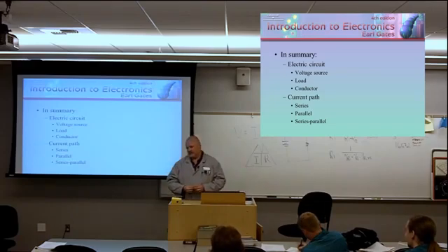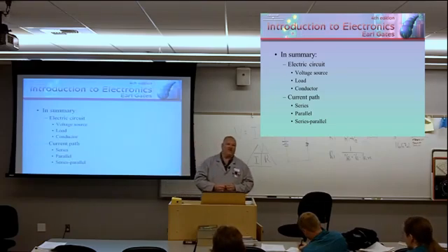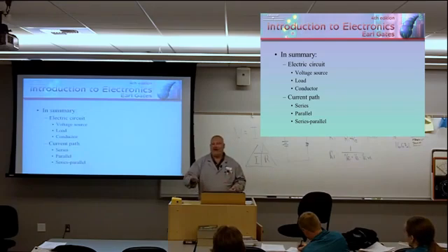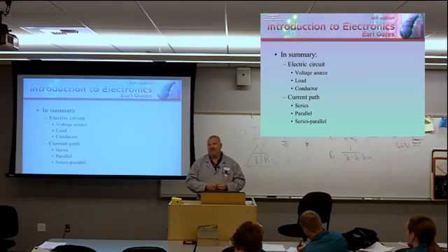Freaking resettable fuse. For whatever reason, there was a glitch that tripped that. You've got to unplug it, totally discharge the whole unit, plug it back in. It reboots thinking it's back at the factory the first day it was ever made. Problem goes away. You've got to make sure you give it overnight to be able to do that.